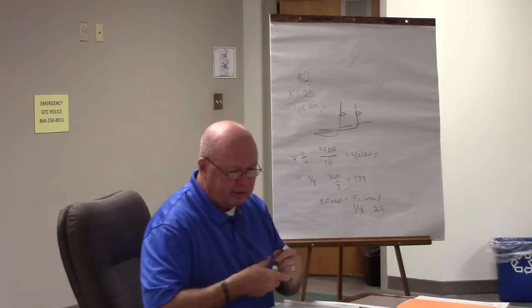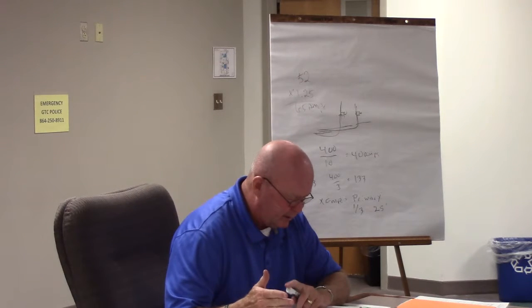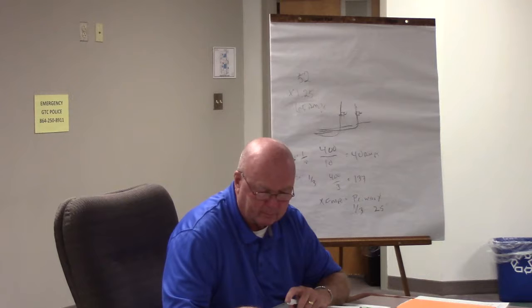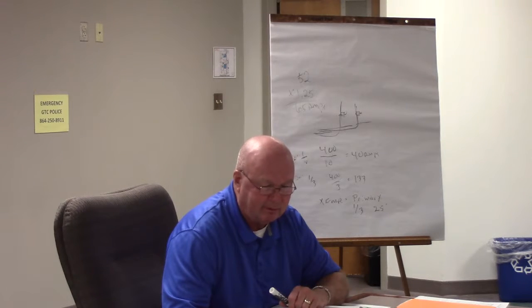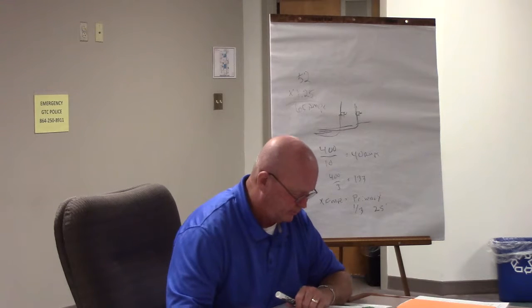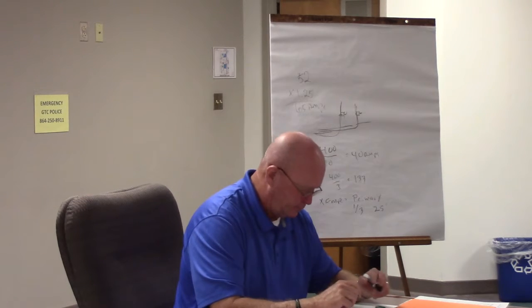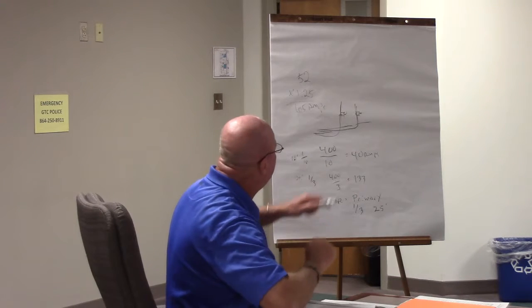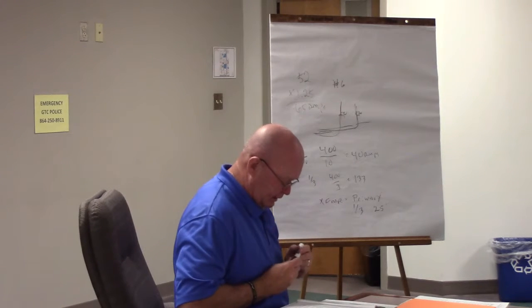All right. Now let's go to 310.15(B)(16). And it mentioned 75 degrees, didn't it? So we know 65 amps. If we look at 310.15(B)(16), 75 degree column, I want y'all to tell me what size wire we'd use. Number 6. So that's good for 65 amps, isn't it? Yes, sir.